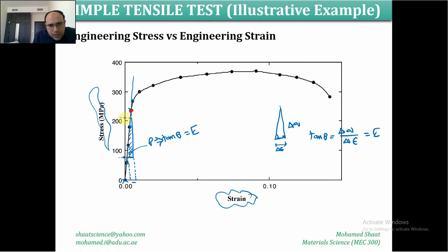So we do have this point, this point, this point, in addition to this point. Choose any two of these points to set up a triangle between them and calculate the elastic modulus from this triangle. If I were you, I'm going to choose, for example, this point, and the other point is going to be 0. I always put the 0 point as one of the two points.